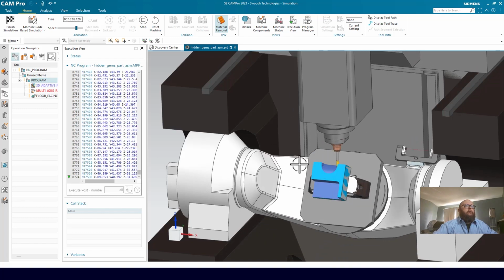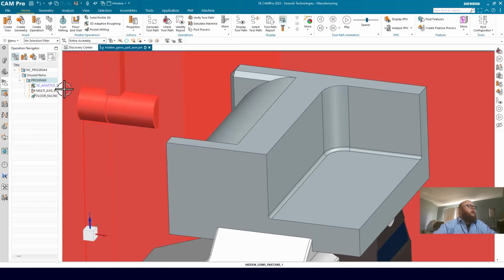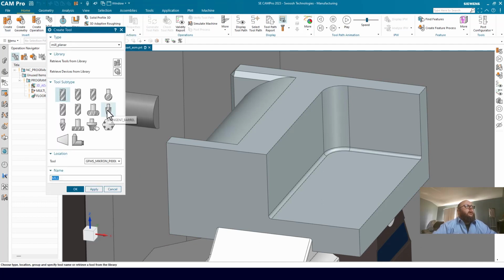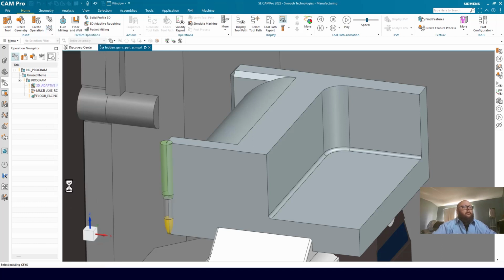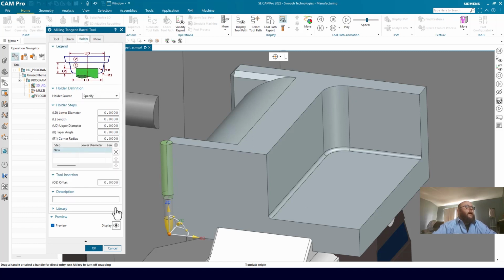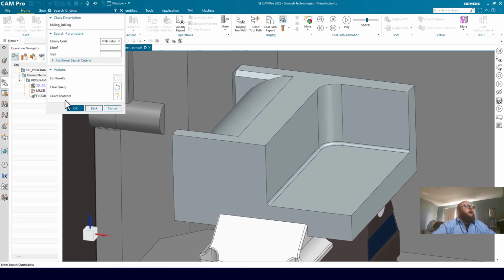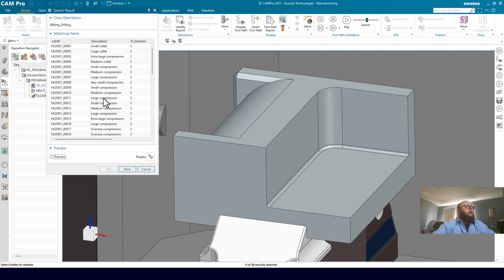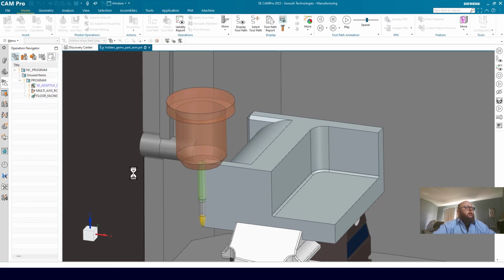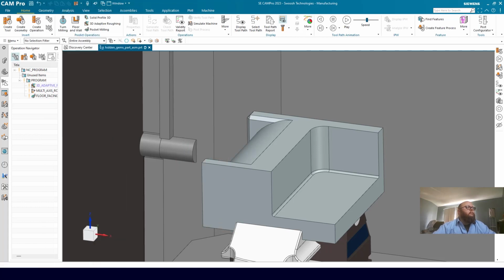All right, we have a couple good roughing operations, facing, things like that. I'd like to do a couple more toolpaths here. Let me create a new tool first. I'll create a tangent barrel mill. Everybody's excited about barrel cutters and finishing with them, and with good reason. There's a lot of time savings available to us. So NX CAM Pro does support these types of tools. I will pull in a tool holder. Yeah, that would be fine for what we're doing. We'll push our tool inside a little bit, and we'll be able to check our clearances later.